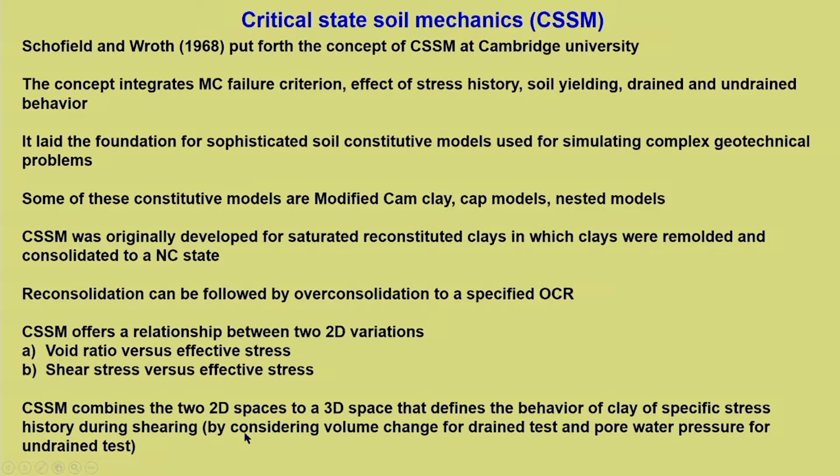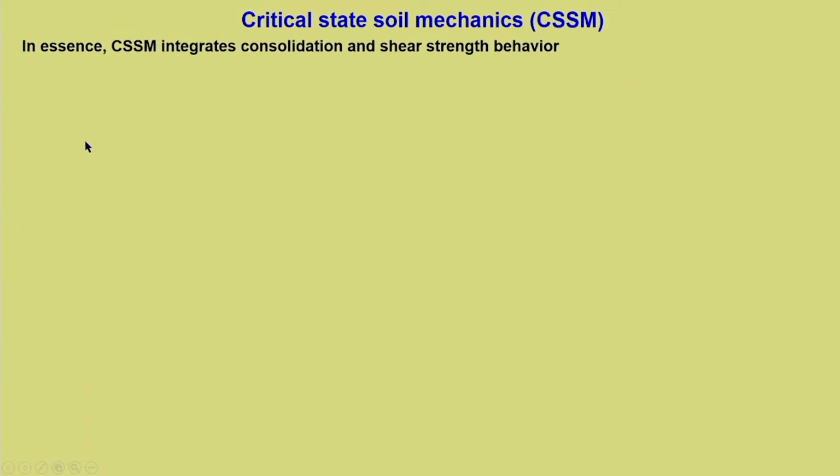For this, the volume change is considered for the drained test and the pore water pressure for the undrained test. So, everything is accounted for in this model, be it the influence of stress history or the influence of drainage conditions, all in one, and we try to understand the soil behavior in a unique manner. That is the whole purpose of this development. So, in essence, CSSM integrates consolidation and shear strength behavior.